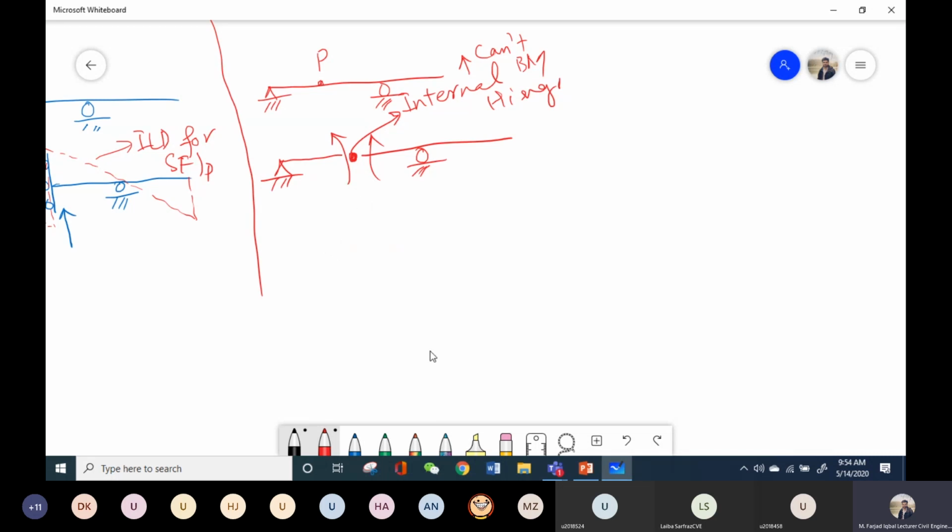In all types of questions, just follow this same sign convention. Then I have to note down the deflection of this beam. What will happen to this point if I hold it from here and rotate it counterclockwise? This will move up, right? And this part will move upwards as well, but it will pass through the support, because the support won't allow it to move upward, right?